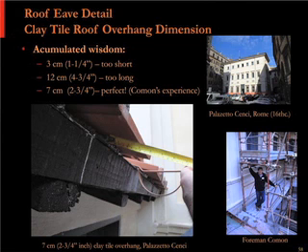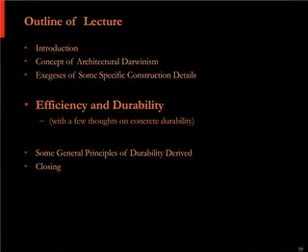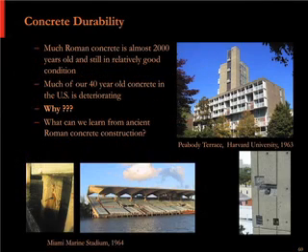That's perfect, because if it's less than that, the water curls around and gets the wood wet, and we find the wood rotted. And if it's longer than that, when we come back out here, we find the tile is broken because someone leaned on it or stepped on it or put a ladder on it, and it was just cantilevered too far out. But 7 or 8 centimeters, that's perfect. It's kind of the Goldilocks dimension. So that was early on. Every time I got on a building, I put my tape measure up. So later I was on buildings by Bernini and Borromini. Sure enough, they were spot on. The tile overhang was 7 or 8 centimeters.